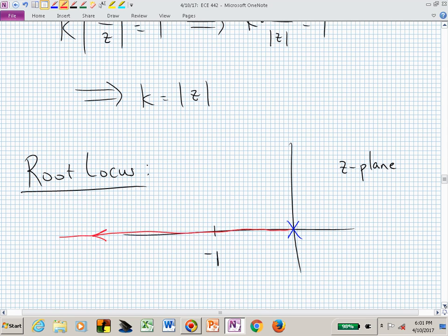There's two real line segments because I have split the real line with that pole at the origin. Now both of those, I'm just cutting my infinitely long piece of bread, and I'm cutting it everywhere I have a pole or a 0. So I've now cut my real line right there. And I'm saying which of these segments belong to the root locus? The positive half or the negative half in this case.